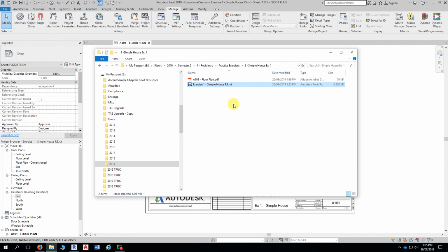So what you do from here essentially is delete any other Revit files that have numbers in them, because they are backup files, they're not required now. So this is the completion of the exercise. So what you're left with is the primary working file here. Any other files with this file name with numbers in it can be deleted because they are backups.